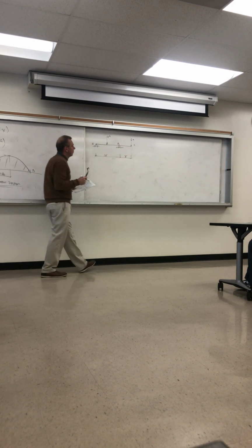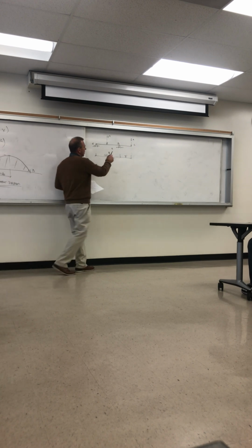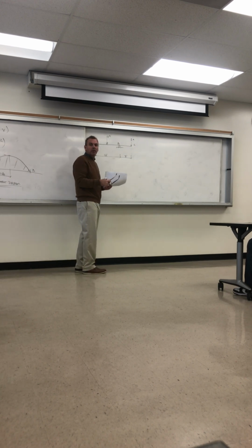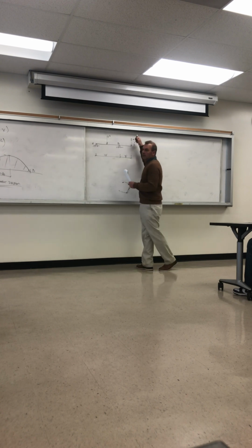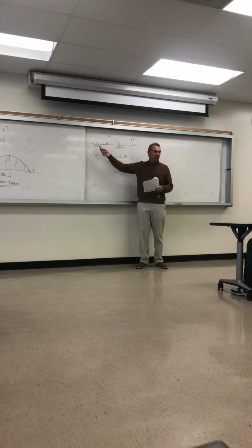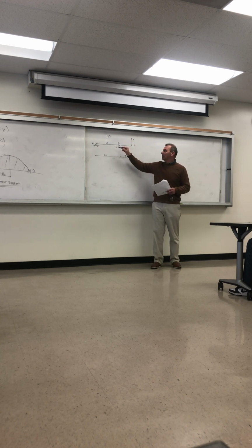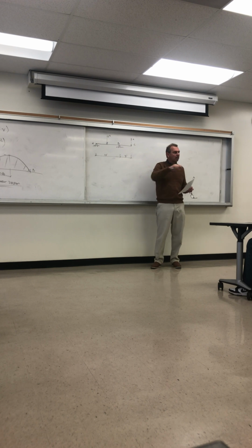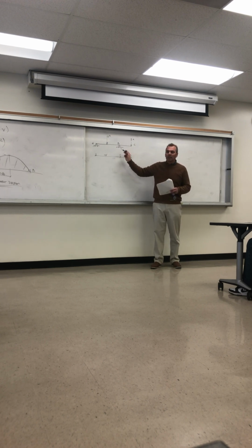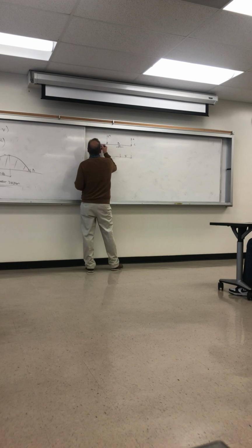The deflected shape, now this is interesting, the left side's a pin, and the right side, not the full right side, but B is a roller, but it continues over the roller, and there's a load here. Since this is the end of the structure, it's a pin, there's going to be 0 moment. But then over here, there's a force times this distance of 3. So there is a moment in this location because of the bend, and we know what it's going to be. It's 5 times 3, 15 kip-feet. It's negative. The deflected shape is something like this.